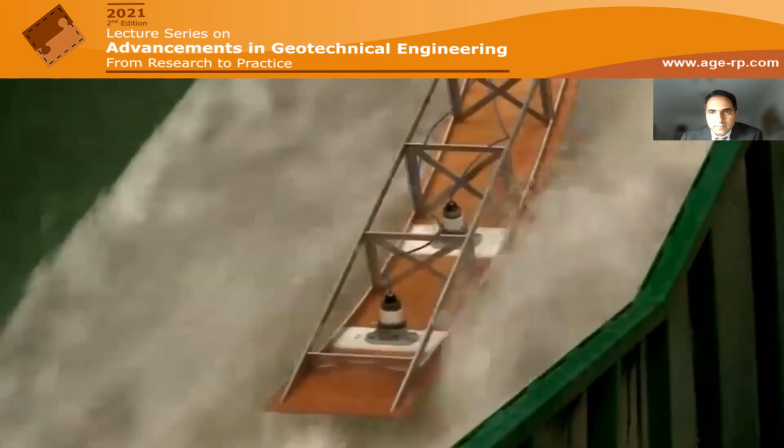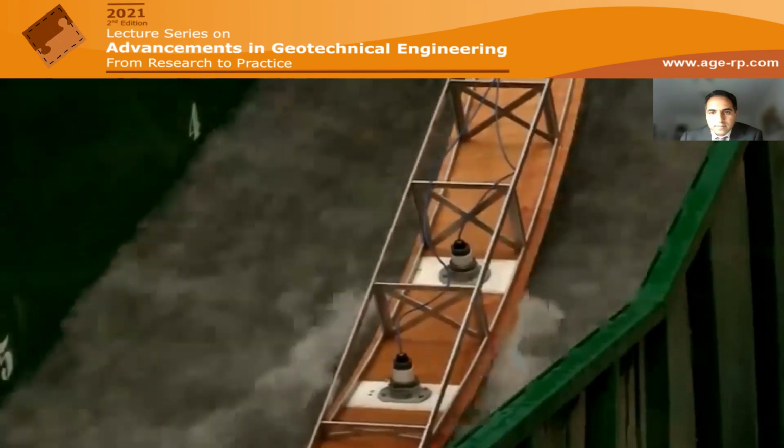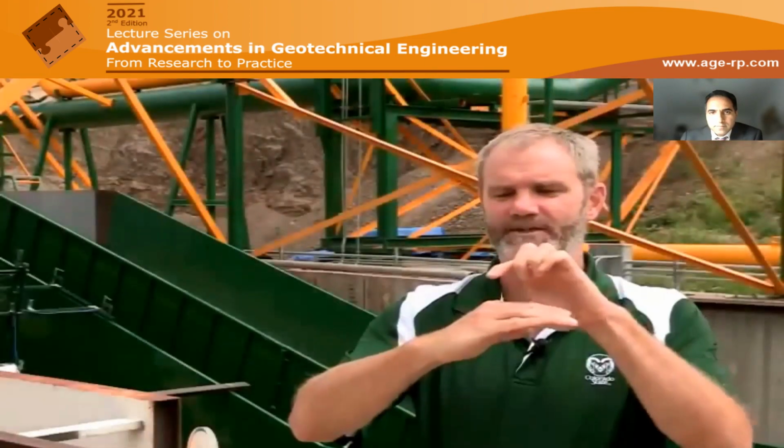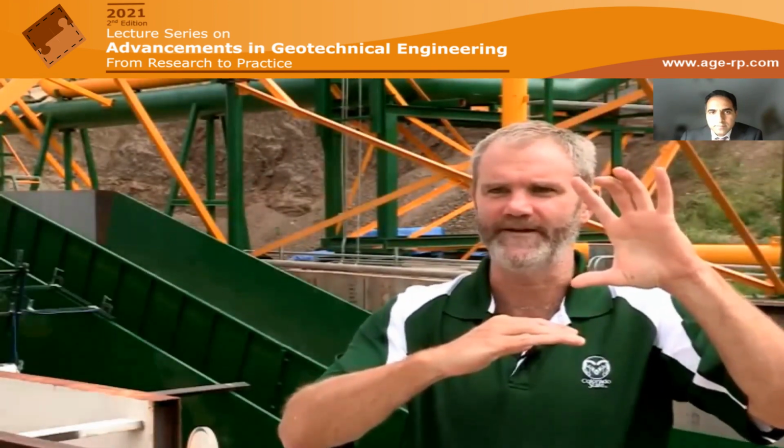So as the waves form in the ocean, they hit the levee, crash across the top, and accelerate down the backside. We're simulating that depth and velocity at the crest through a tank that sits above the levee. Based on Katrina, we saw that there were a lot of various levee failures, and so now we're trying to go back and figure out why that happened in more detail, and also what we can do to prevent that from happening in the future.